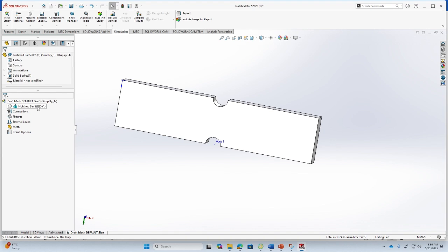All of these steps up till meshing are called pre-processing. The step of solution is called processing, and then any analysis of the graphs afterward is called post-processing, okay. In old days, we used to have separate softwares doing all of these three tasks, okay. But now things have changed. Software is much more advanced, so we can do everything in a single interface, okay.